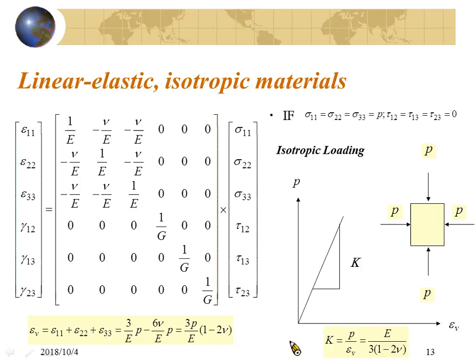So you will find the bulk modulus can be expressed as a function of Young's modulus. This will be a critical element. The volumetric strain will equal epsilon 11 plus epsilon 22 plus epsilon 33. This will be a very essential relation. I think you already learned why.